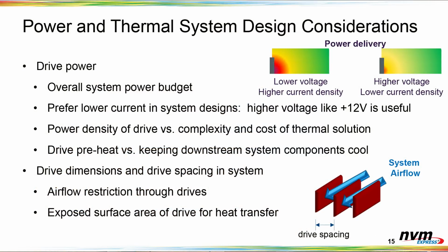Okay, another consideration, drive power. Your overall system power budget obviously is really important. 25-watt drives with U.2 was a challenge when we first started seeing those versus the 12 watts I think the industry was used to with 2.5-inch. And it's really about unlocking that performance. That was fine, especially when we were using SSDs as an accelerator, a cache. Even adapter cards were popular at those 25 watts, even maybe plus. But it was really a cache or I/O accelerator. Now we're moving flash to more as main storage.